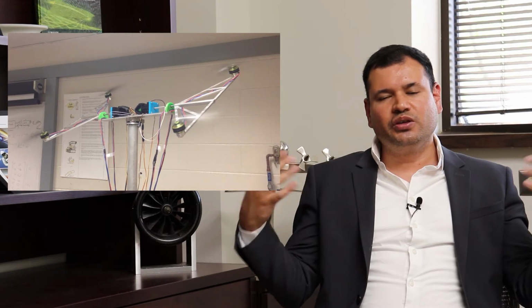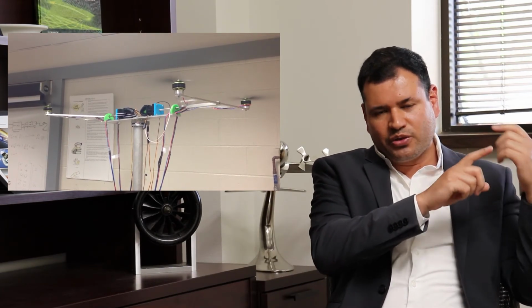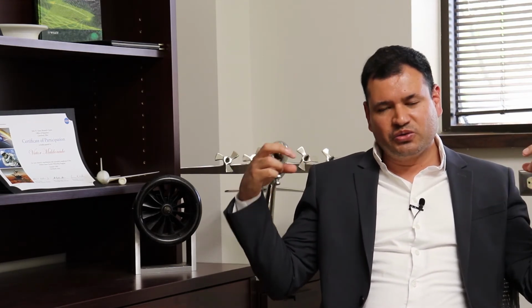So what happens is that even though you send the same commands to the arms, the rotation of the arm happens by throttling each of the two rotors, the one on the front, the one in the back. And by this differential thrust, you're able to produce a net torque that rotates the shaft of these two arms. However, they're not synchronized together just because there's variances in the way that these two systems are designed.